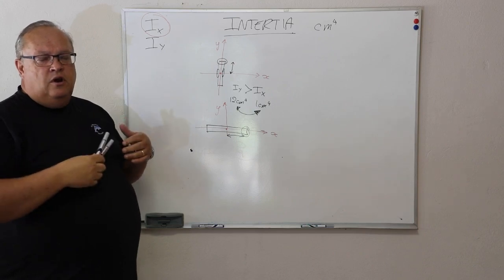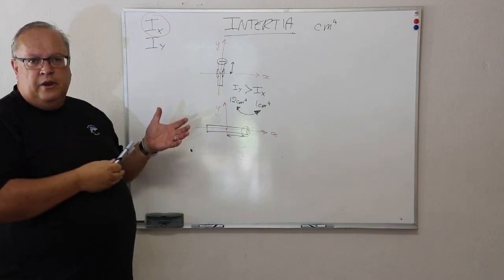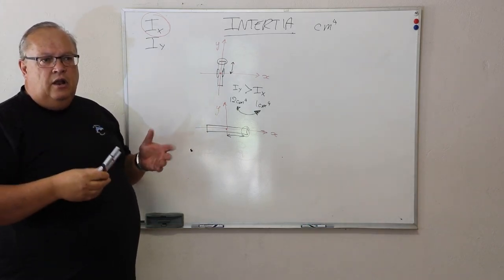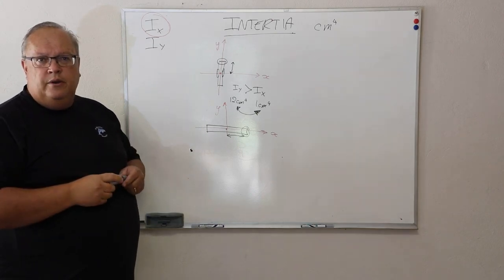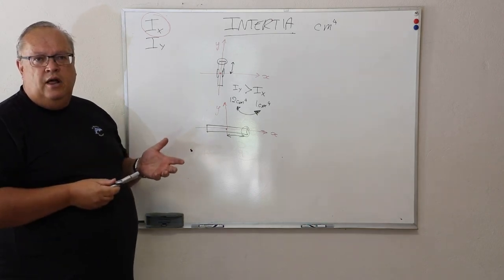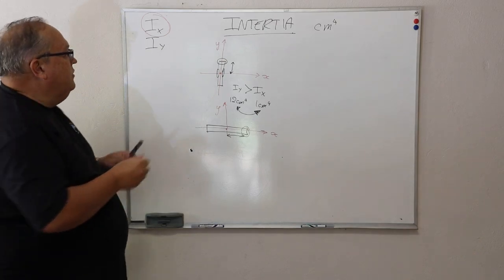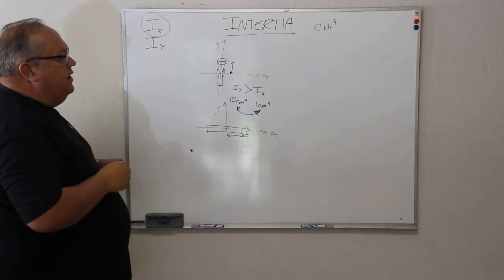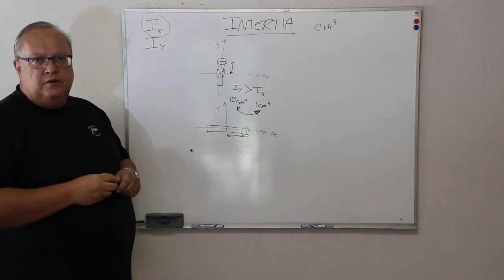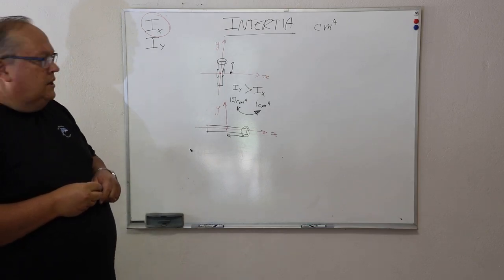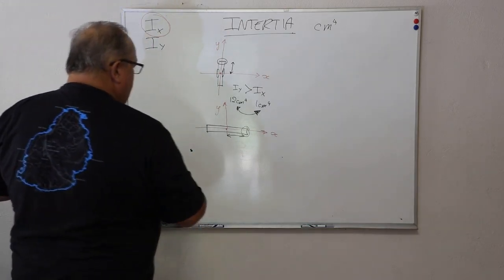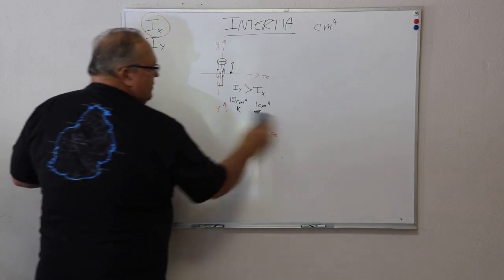And if you go into StarFront and you go into the edit menu, go to the section file, you call up any of the aluminium sections on that file, you will see the Ix and Iy value of every section listed for you. So let's understand, for example, how this affects the selection of mullions.